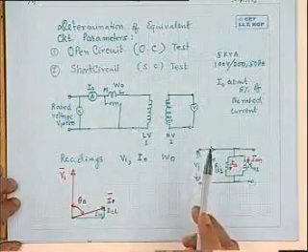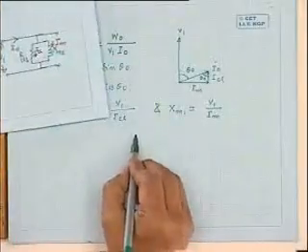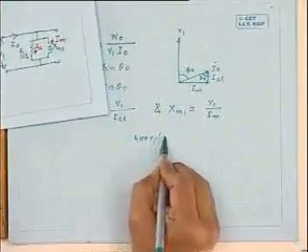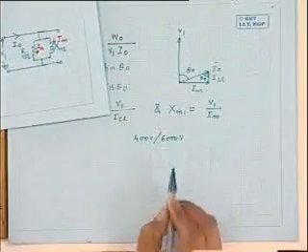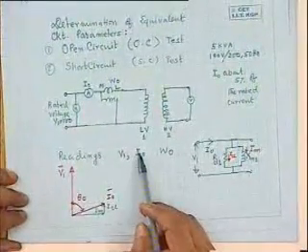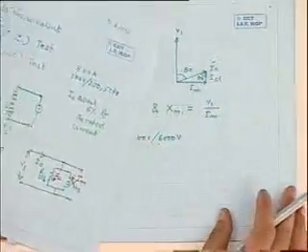But if the rating of the transformer is, say, 400 volt stroke 6000 volt, then it is better to carry out the test from the LV side, because in the laboratory you may not have this 6000 volt available, or even if it is available, it may not be very safe to operate. And also, if you want to energize the winding with the rated voltage of 6000 volt,